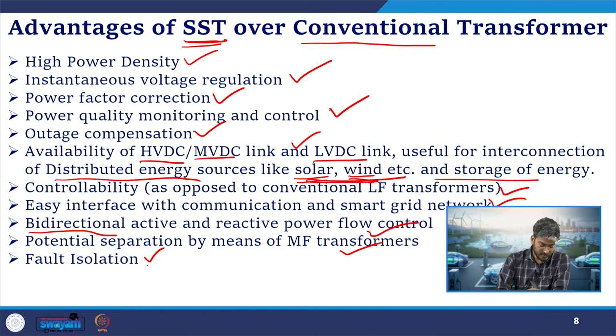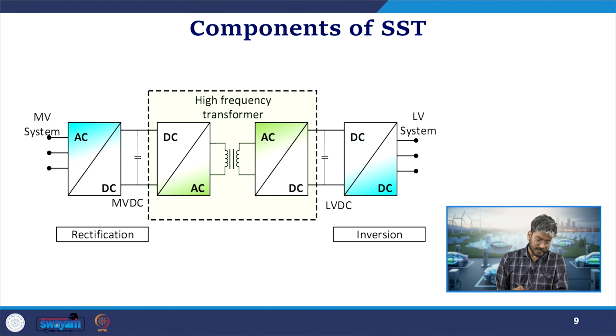So whenever there is a fault detection, I will set some contingency signals in the DSP, or send some contingency signal to the controller, and it will automatically bypass or disconnect the faulty section from the healthy part of the circuit. Once there is a fault on the primary side, it will ensure that no current flows from the secondary side into the faulty side of the system. So that facility is available with our SST.